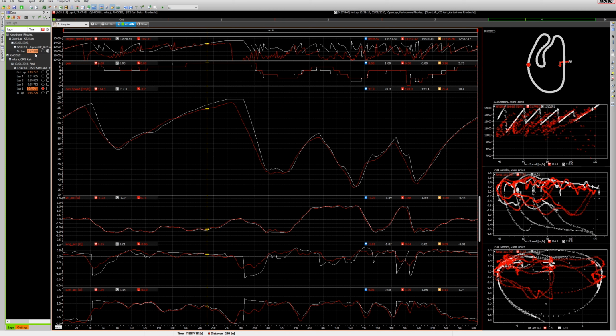So the absolute number of the lap time shouldn't be something you look at, but what simulation basically gives you is relative differences in lap time when you change something in the setup. And that's what you need to look at in general. Now, in terms of correlation, here the speed channel shows way more differences than it did in the Super Trofeo case, with the main differences being seen here in the GG circle. If you look at the braking deceleration that Mike can achieve, which is about 1G, while OpenLAP can actually brake with about 1.6 or 1.7. At the same time, in reality, 1.6 Gs are achievable while cornering.